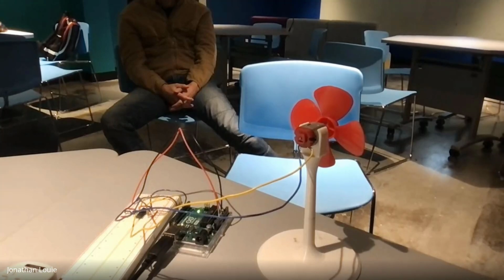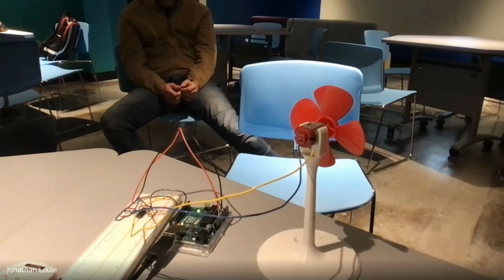Oh wow. And actually, as they get smaller, some of the economics of the electrical operation work better, because you need fewer electrons to charge a smaller wire than a bigger wire. So especially for digital, where you're not switching too fast, it can just overall be more efficient to go smaller. As frequency goes up, you start getting emissions effects, and you go into transmission line engineering, which is a subset of electrical engineering.